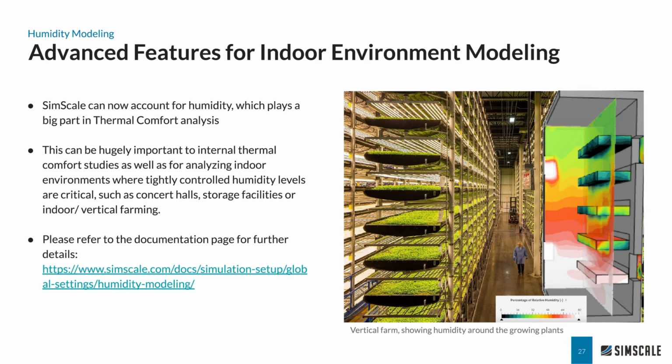And for me, one of the most interesting new additions is the full solution of humidity on SimScale. This is something that not every CFD tool can do very efficiently. With this new addition, we can add humidity not only to inlets and outlets of our domain, but also as sources inside our flow domain.